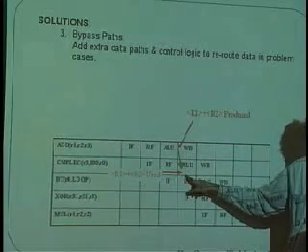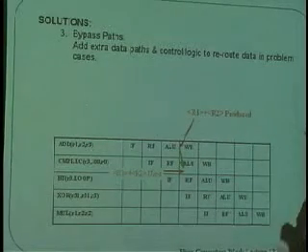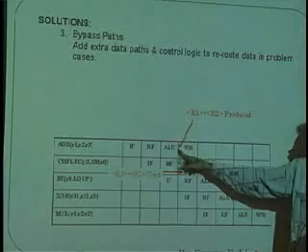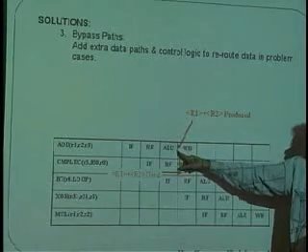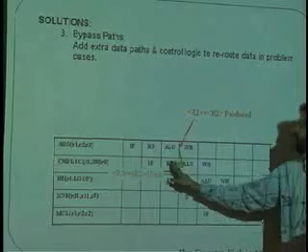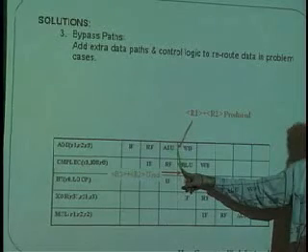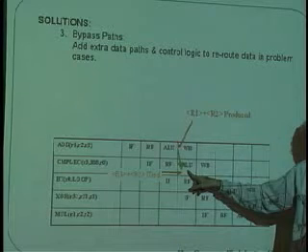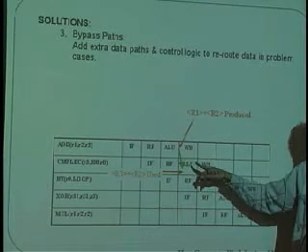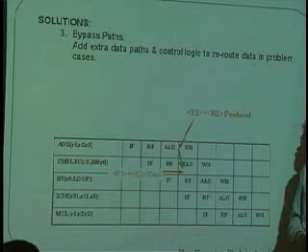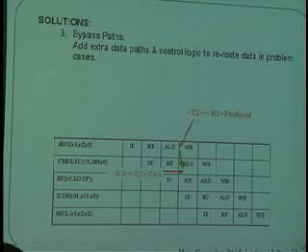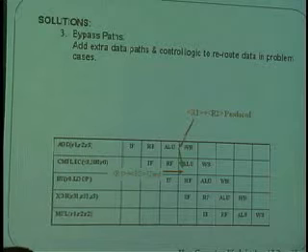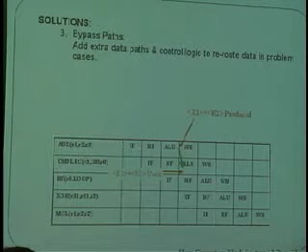And so maybe what we could do is short circuit a path in the machine and steal the data from here, clobber the answer that we got from here, and sneak it into the ALU before the ALU actually used the data. And believe it or not, this is done all the time. And this is called a bypass path. Okay? And the idea here is that it's an extra data path and some quite sophisticated control logic in the machine.